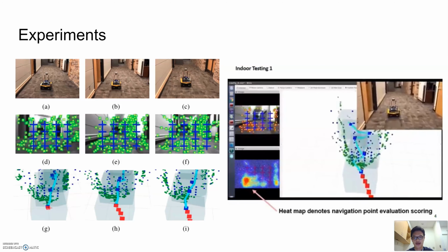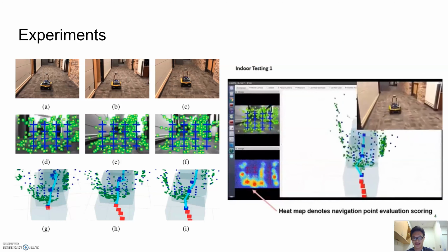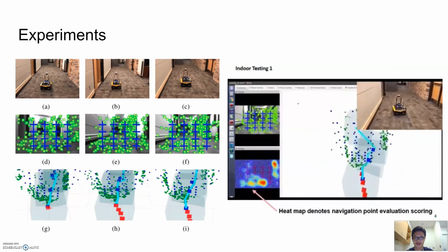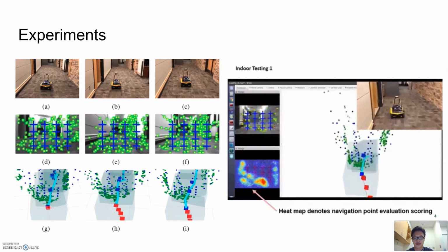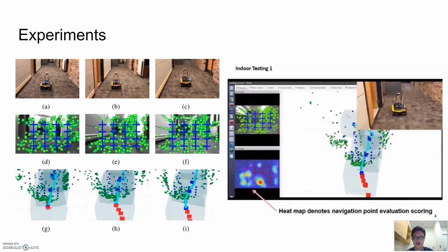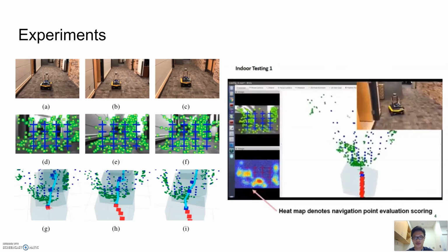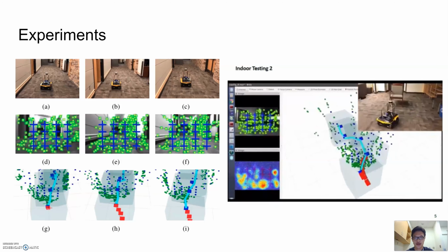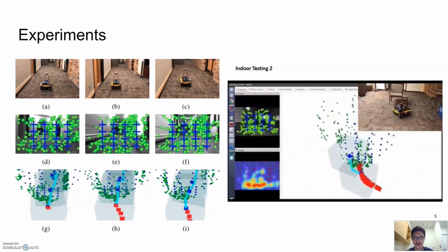The indoor navigation experiment shows that the proposed convex hull growing method is effective and fast in constructing free space in the presence of sparse and noisy maps. Therefore, the proposed approach contributes to a lightweight safe navigation framework which is essential to autonomous mobile vehicles, especially when other high-definition ranging sensors are not available.